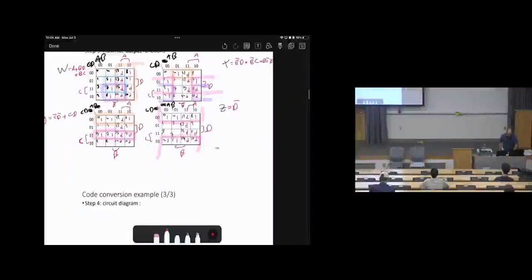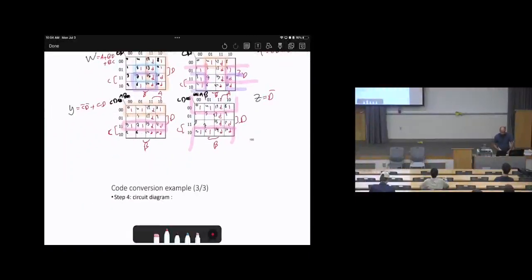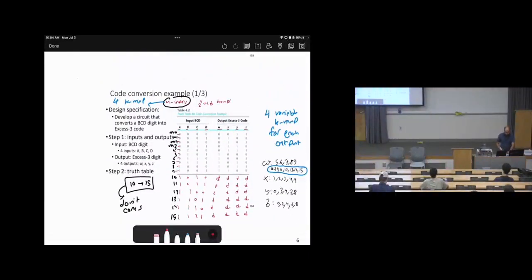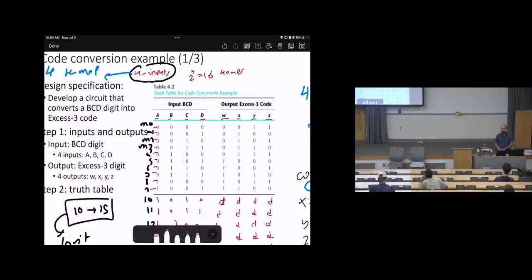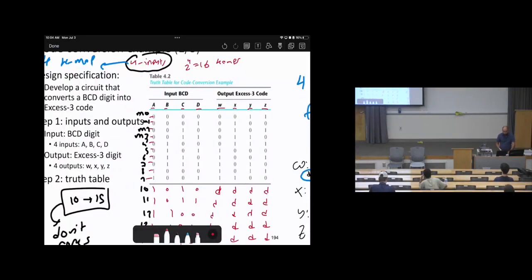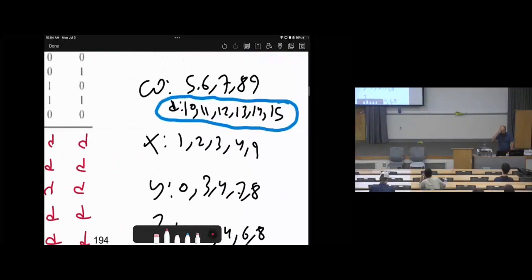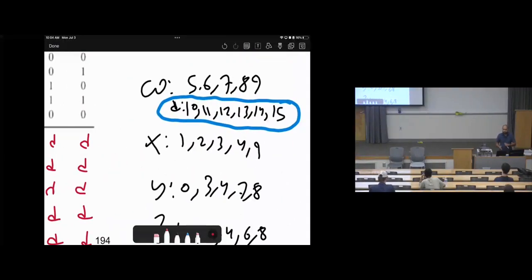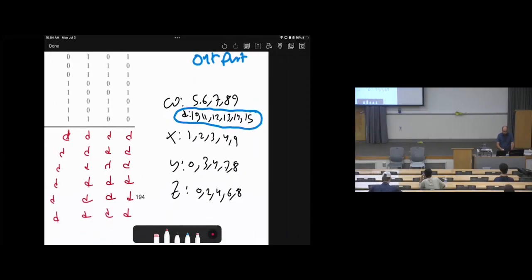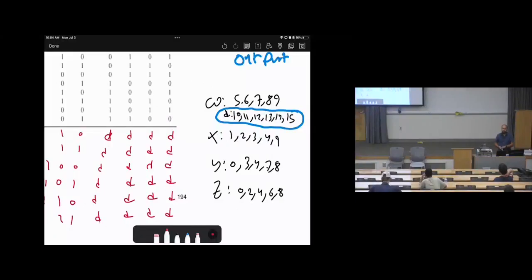So in our design, the first part, we have the inputs, put the outputs. Then we determine the min-term list. If you need to draw these circuits in canonical form, not the simple form, we can just draw it using the min-terms. But our target in design is to make it as minimum as possible.